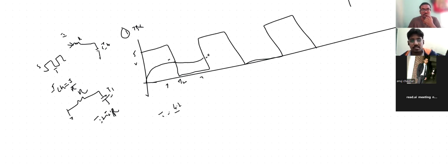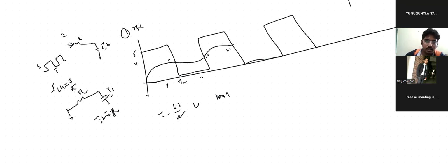So this cycle goes on like this now. We can observe that our charging current will be reducing and discharging current will be increasing. We can observe this kind of trend. Maybe this can go till again 1.1 or 2 volts, suppose. After some time, at steady state, the thing when I say the word steady state, it will be when both charging current and discharging current are the same. That is in this case at V in by 2. Suppose my capacitor is charged till 2.5 volt, my charging current will be 2.5 by R, and similarly discharging current will be 2.5 by R in the negative direction. So there will be no more charging and discharging. So the steady state output voltage will be 2.5.